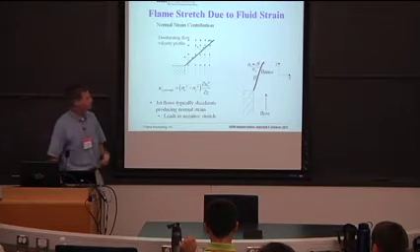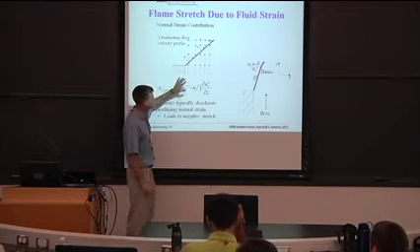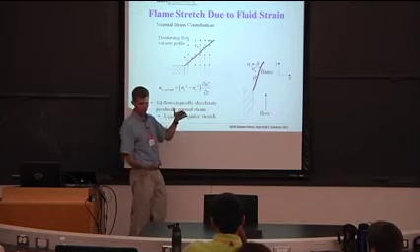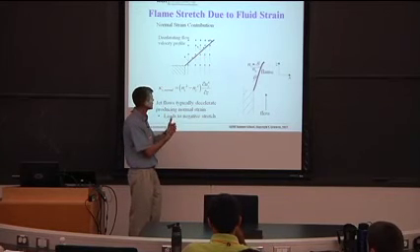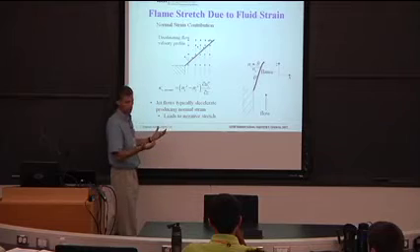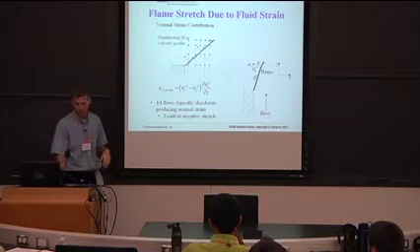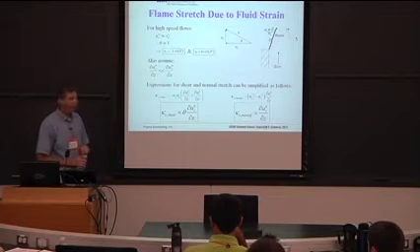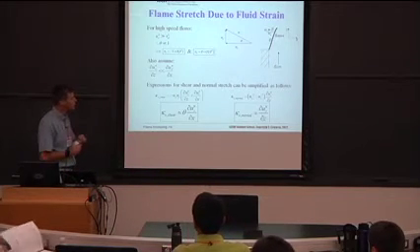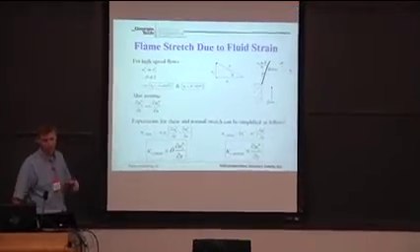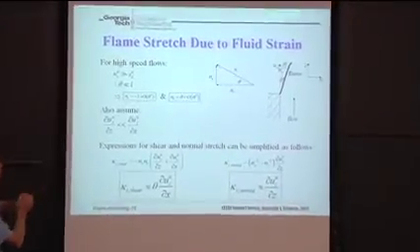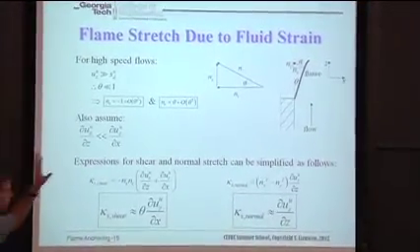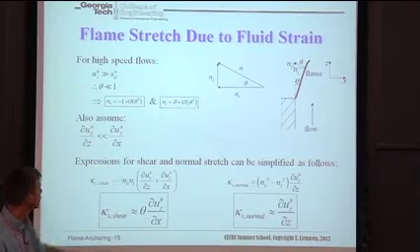By the way, the reason I'm talking about this is that for any flame in a shear layer, like I said, you'll almost always have some flow deceleration. All right, so again, I have some math here, so let's take those same ideas and try to figure out approximate scalings for how fluid strain is related to flame stretch. I'm going to skip over the details. I'll let you look at these.